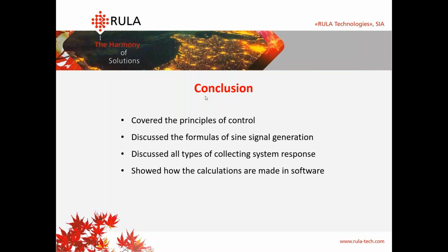Are the principles and formulas the same for different test types like random? The control theory is the base for our tests, but regulation and generation is different for our tests. For example, in a random test, we regulate frequency response, not the amplitude. And I think we have another question about the compression.